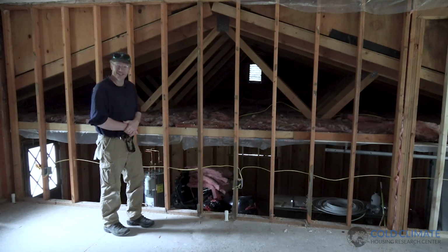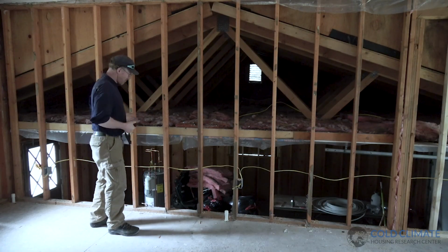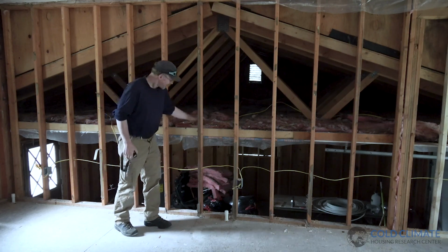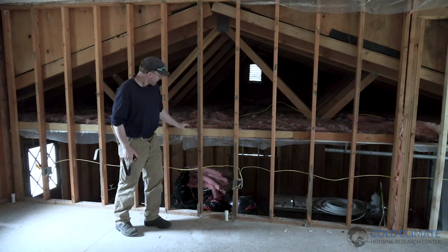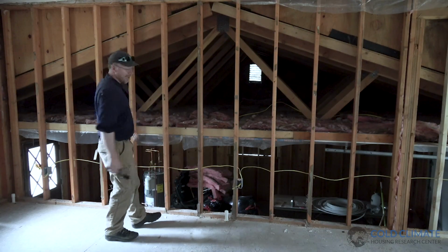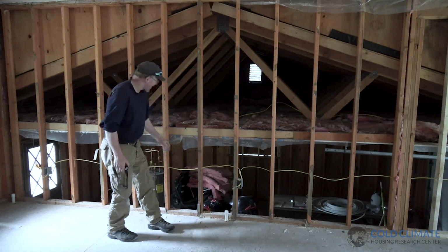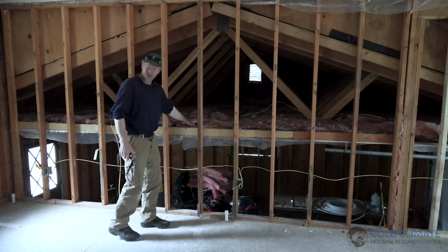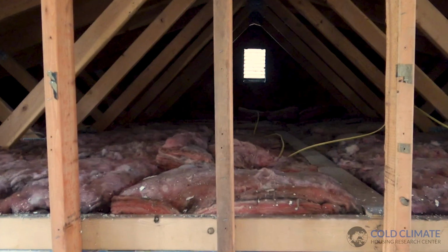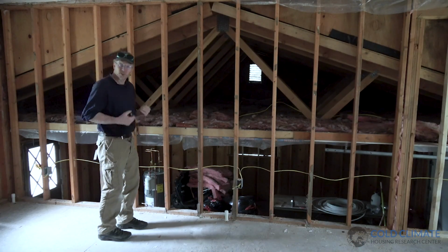I'm now standing inside the living room of the house, and we're right here at our problem area. This is our air leakage related thermal bypass. This wall has obviously been gutted down to the studs. I've got a clean view here into the garage. I can see and reach into the garage attic. It's woefully under insulated, by the way. This looks like our R-19 fiberglass batts. What's problematic, though, is how this wall was air sealed.